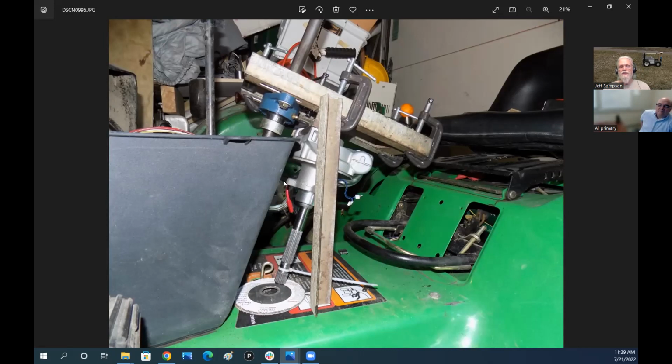And down here on the face of it, there's some tapped holes. I could just put a piece of steel through there and bolt it on, and then some of this stuff I'm putting on here, just weld it on. So I could run a brace across that, which number one would make it stronger, and then this strap there will keep the motor from rotating this direction. So once I get to that point, then I'll know if that's close enough that it's going to work.